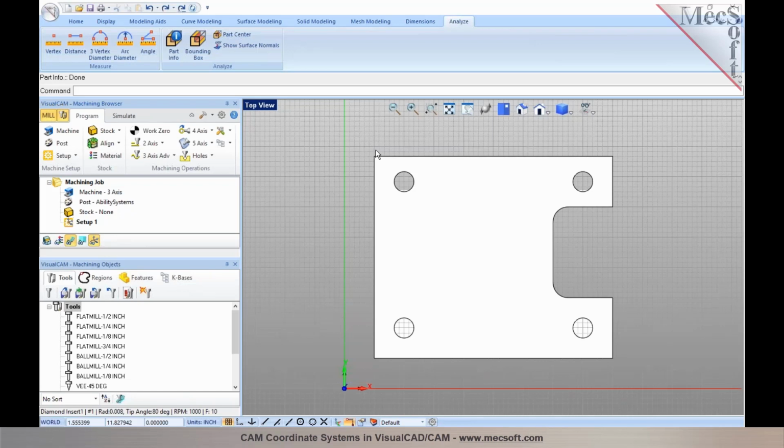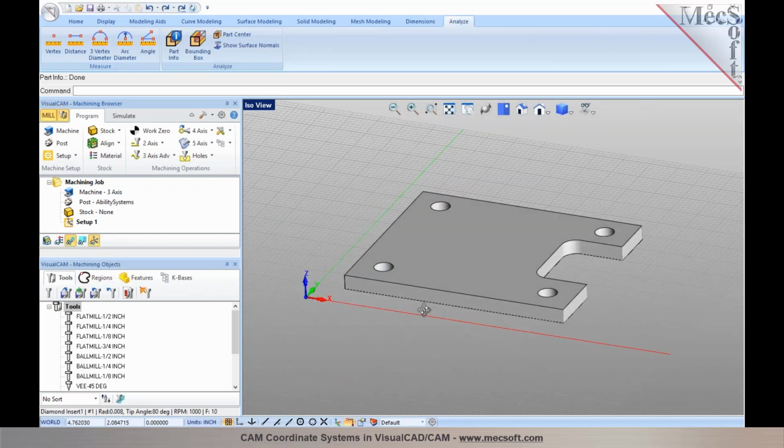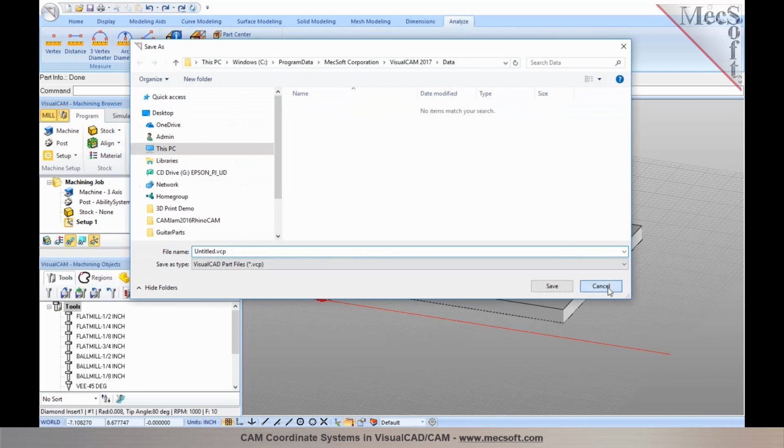The orientation is the orientation in which the part needs to be placed so that it is suitable for machining. In this particular case, the length of the part is parallel to the x-axis, which means the longer side of the part is along the x-axis and the shorter side is along the y-axis. If the machine tool you're working with has more travel on the x-axis compared to y, then the way we currently have this part oriented looks right. So we don't need to rotate or do any additional transformations.